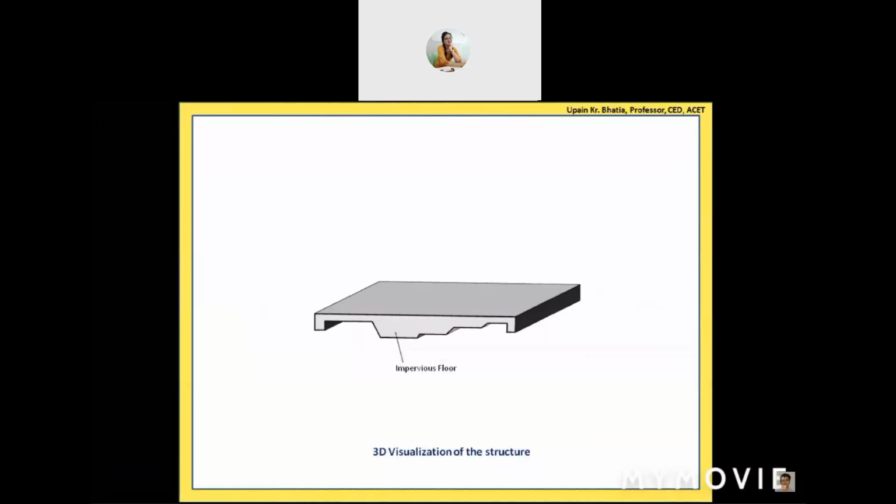This floor is designed before actually providing it in the field. So the thickness, which is shown at various points, is varying: in the middle it is thicker, and on the downstream side of it, you see that the thickness is reducing. Further downstream, it is reducing further, and at the end and on the upstream side, we have these thicknesses. Why and how these thicknesses are provided, we will calculate again in the seepage theories, the subsequent lectures.